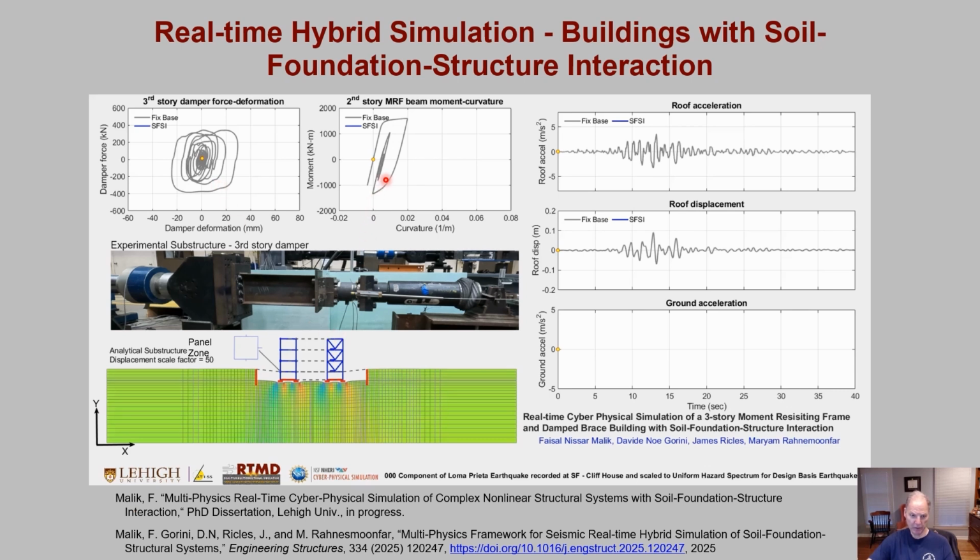We have the moment curvature relationship at an integration point at the end of the left-hand side second story beam. And we can see a few degrees of nonlinearity occurring in the moment curvature. It's got a local ductility of about 2, not too bad, but it's there. This is in the RBS connection where we actually expect, if any, some yielding.